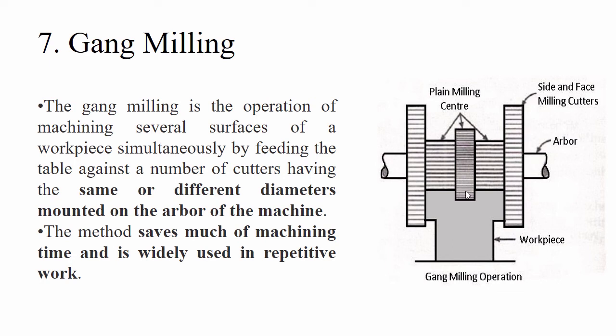So what I can conclude here is, in gang milling you can use tools of different diameters so that you can produce a workpiece of desired shape. That is what I have mentioned here. In gang milling, cutters of the same or different diameters can be mounted on the arbor. Here you can see all of different diameters.